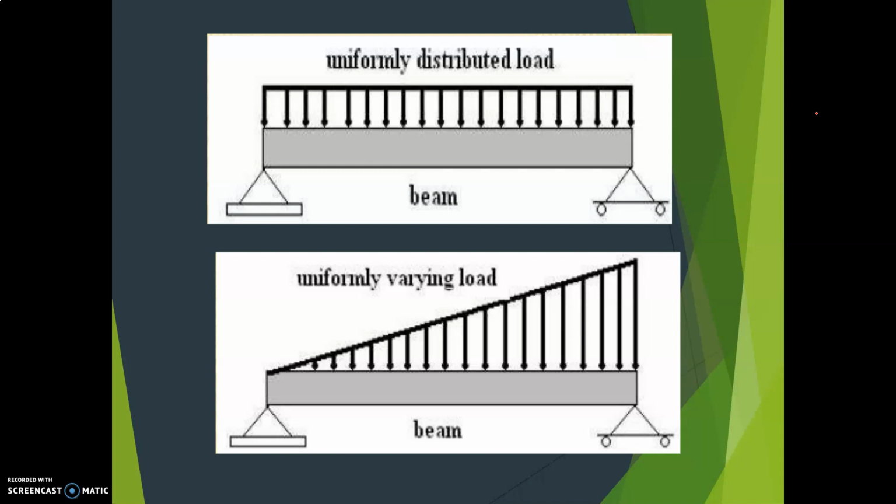Okay, and also if a floor slab is supported by the beams, the load of the slab on the beam is certainly a uniformly distributed load. Here, the main thing you have to see is that the self weight of the beam itself is uniformly distributed. For convenience, a uniformly distributed load is always converted into its equivalent concentrated load acting at the center of gravity of the load. So this I will explain in detail while solving the problem.